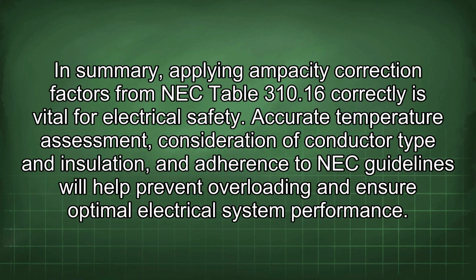In summary, applying ampacity correction factors from NEC Table 310.16 correctly is vital for electrical safety. Accurate temperature assessment, consideration of conductor type and insulation, and adherence to NEC guidelines will help prevent overloading and ensure optimal electrical system performance.